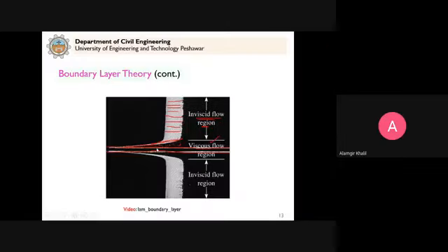So you see that this boundary layer develops when the flow passes, in this case, a flat plate. We consider a flat plate because it's very easy to understand the mechanics of the boundary layer, and because later on we are going to develop different equations, so it's very easy to do that. But this will be for all types of objects. If we have a curved object, then it will be complex. So that's why we commonly consider this flat plate in developing the basic concepts.